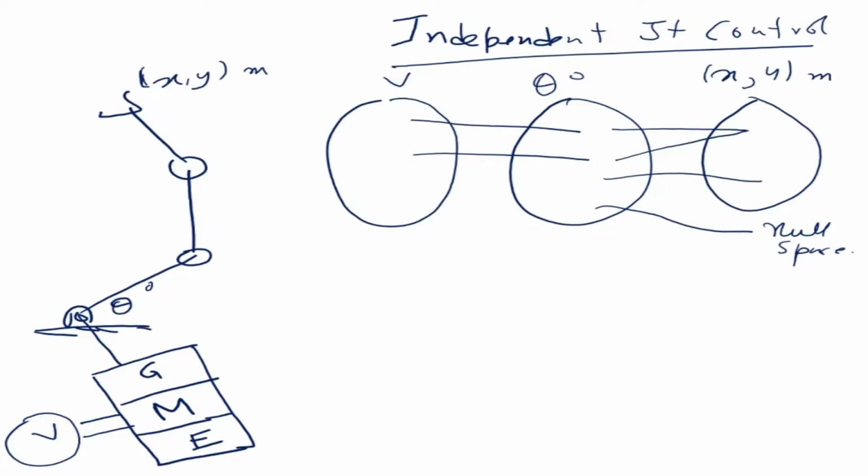Now in terms of geometry, what I mean is, if I were to draw a two-link system here, we have one link here, another link here. Okay, so this is my theta1 and this is my theta2, and this is xy. This is L1, L2. So geometrically, we can find the relation: x is equal to L1 cos theta1 plus L2 cos(theta1 plus theta2).